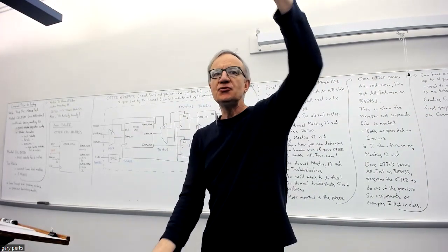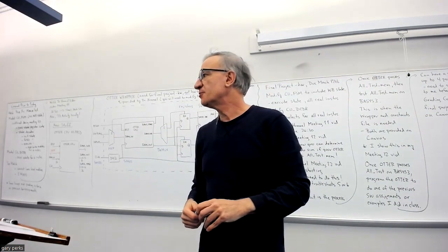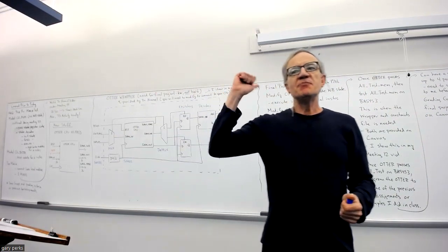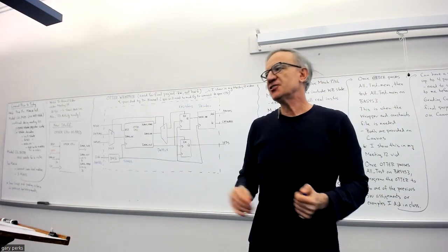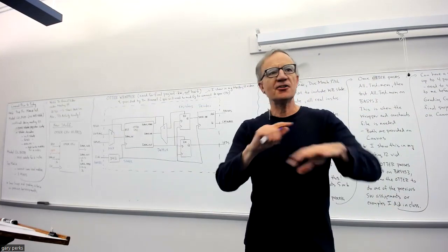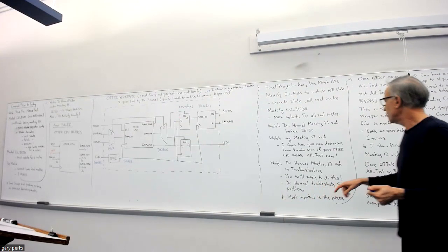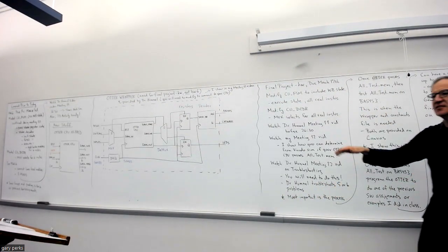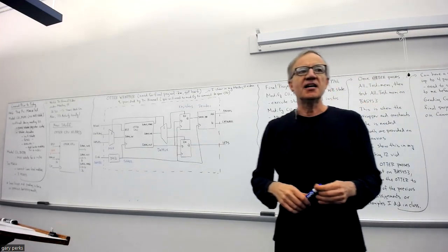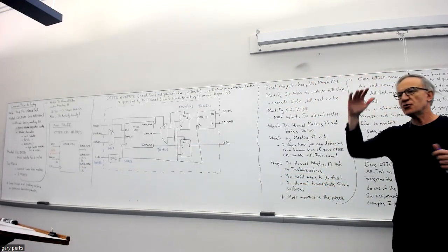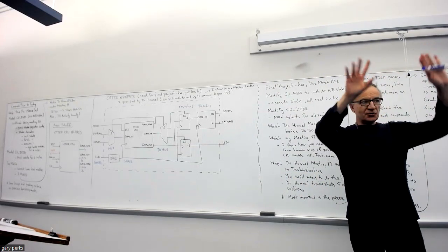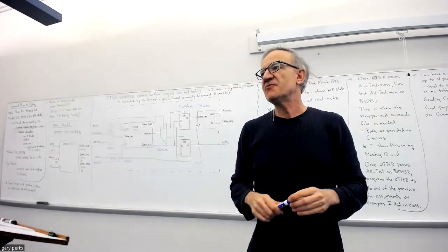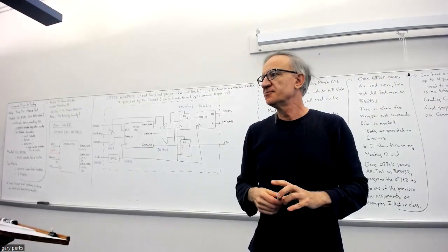You look at it, it's a huge assembly language program with 4,000 instructions. And that mem file tests every instruction. It will test all your real instructions. So if your Otter CPU passes this, that means it's working, okay? And in this video, I show you what you need to do in the Vivado sim to make sure it's running that mem file correctly, okay?